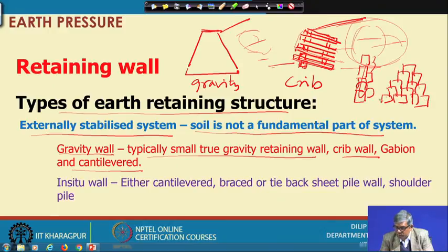These are all gabions. So, it is here, then it will step back, so that stability will be better. A number of gabions will be there on the ground, and the soil will be retained behind. Each gabion will be interconnected, and they are quite heavy, so it is not easily washed away or fallen. They are connected to each other, and each one is also quite heavy. So, all together will work like a wall, and this soil will be supported by this.